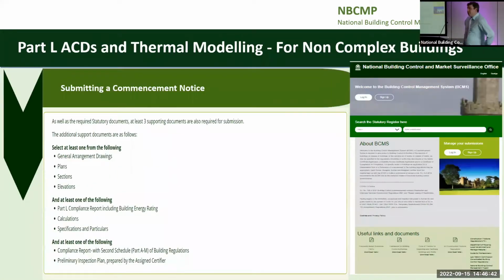Every new house that's got planning permission needs a commencement notice. And you're required to submit general arrangement drawings, plans, sections and elevations, a Part L compliance report or calculations of specifications, and at least one of the following: a preliminary inspection plan prepared by the signed certifier if it's done under SI9, and a compliance report with the second schedule of the building regulations, 8M.